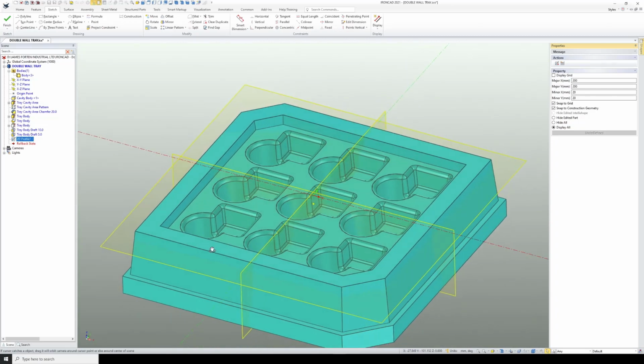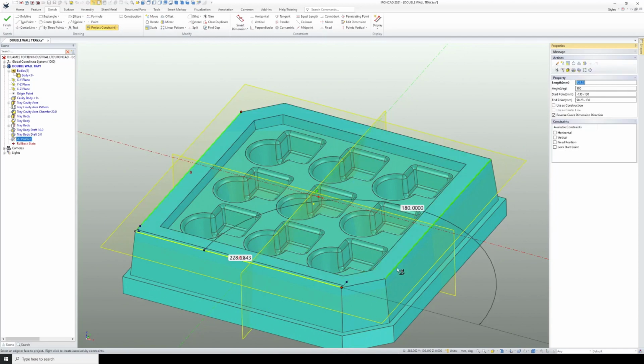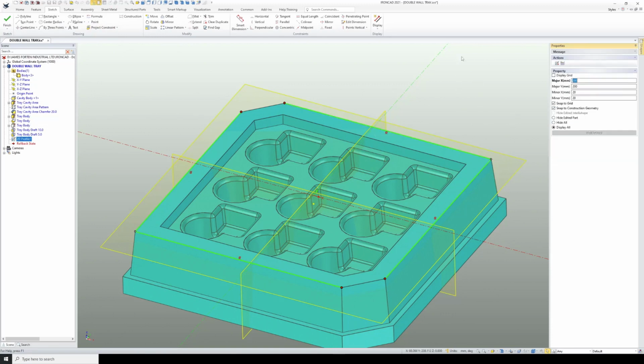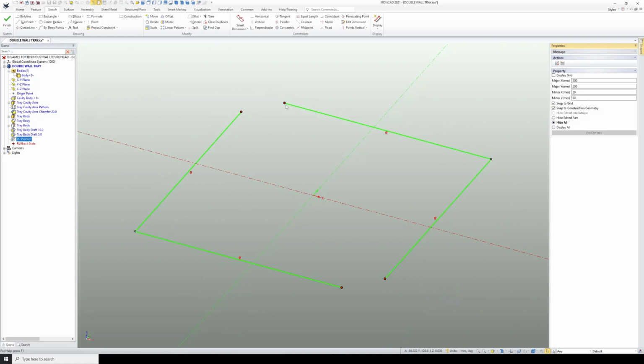And so I want to project, constrain, and this is important. It must be constrained, these edges here. Now I don't want the chamfered edges, so just these edges. So I'll select the tool again to deselect it, or I could push escape. And now I'm just going to select in the sketch in behind so I can hide this geometry. So I'm just going to hide it. And what I want to do is connect up these. And so I can drag the points, but I'm just going to use the extend tool up in the ribbon and select that one there.